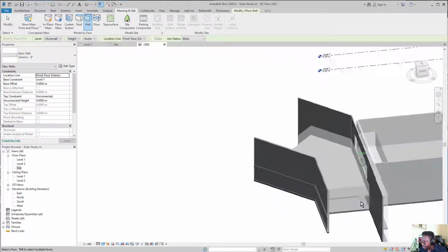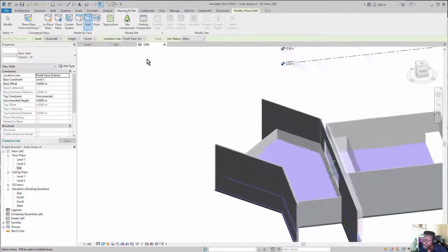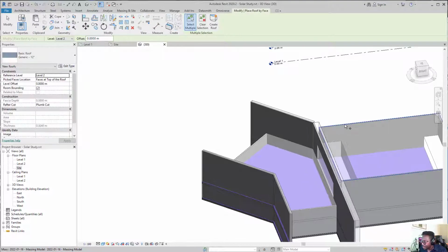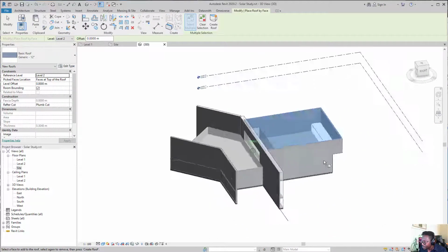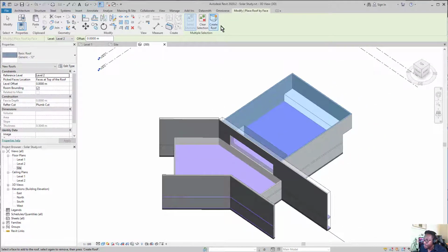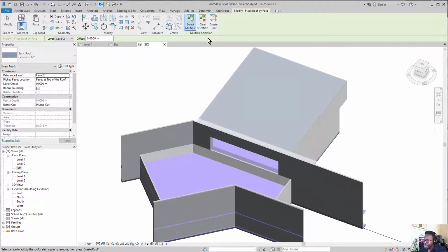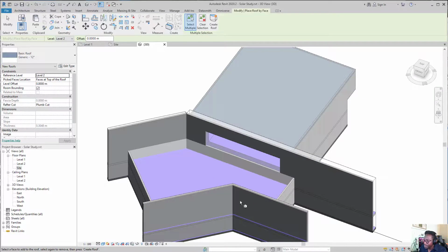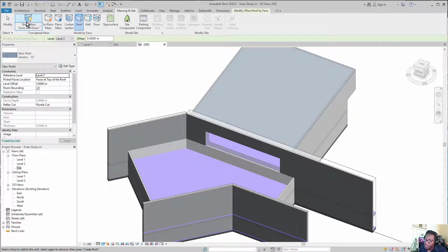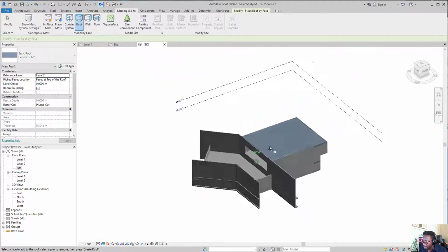All right. Oops, there's another one here, and let's put another one here. And then lastly, we can go to roofs, and we'll put a roof there. All right. So now we need to choose the create roof feature. And now we have actually created geometry that will be used in our model. Now, if I go back to massing and floor, I can click this object here and notice that that shadowy figure is now gone, because we have generated from that shadowy figure actual geometry.